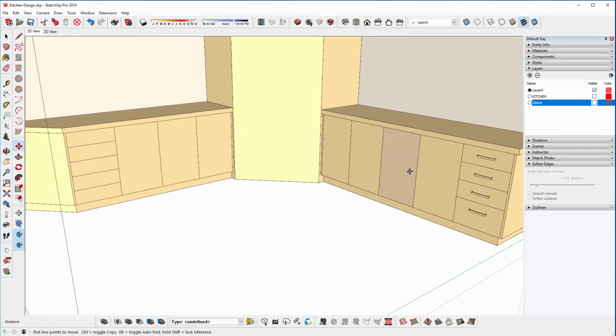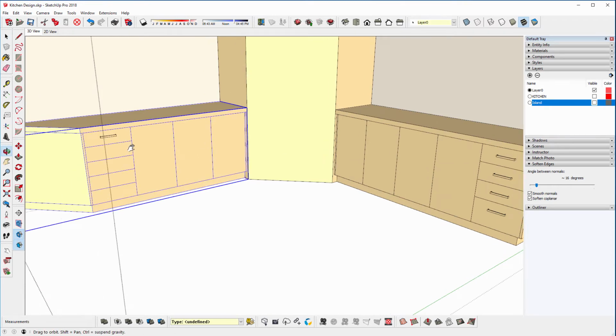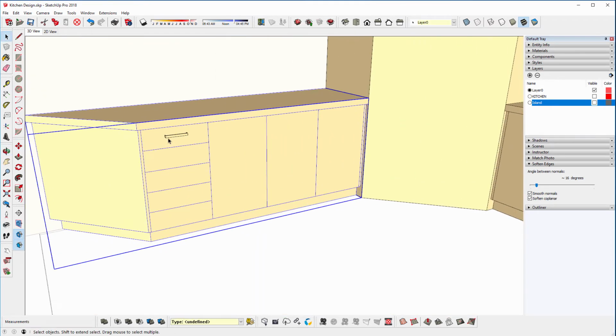If I want to copy that to the left hand side, I could select that, get the move tool. I could use the midpoint there, press Control, click, and it will automatically find the other face because it's glued to any face. Since this is a surface, oh actually it's not even a surface, it was in its own kind of group, but it still found the face.